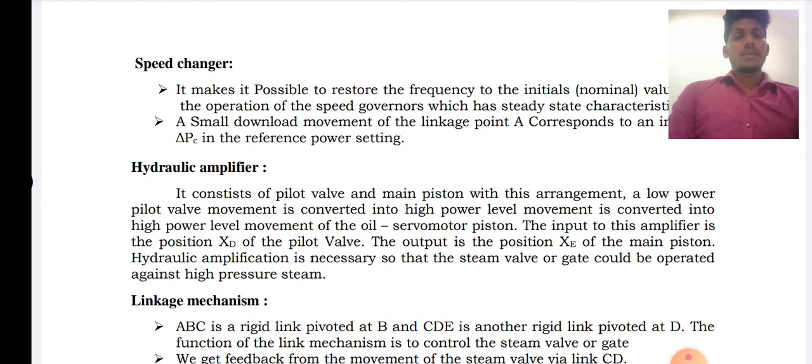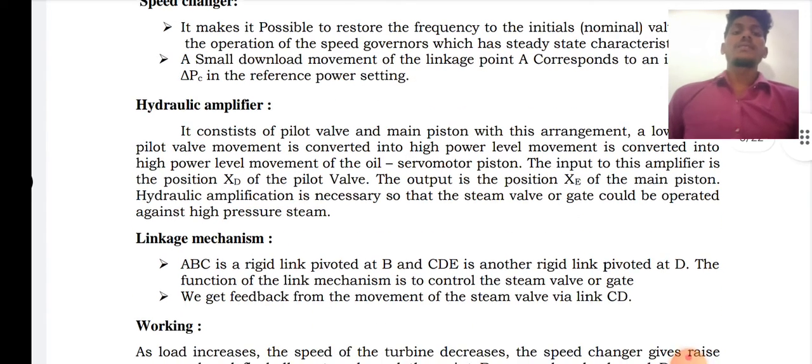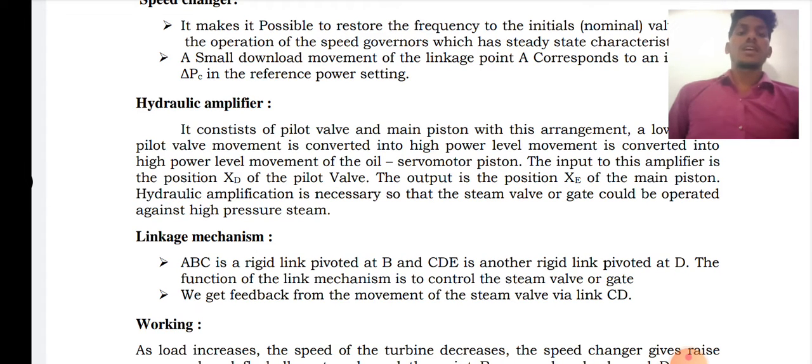Low power pilot valve movement is converted into high power level movement: the pilot valve output position xt is converted into the main piston position xc. Hydraulic amplification is necessary so that the steam valve could be operated against the high pressure of the steam.